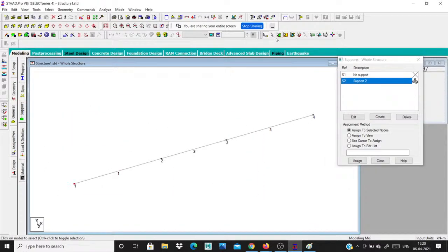First of all, this is a beam cursor, and this is the node cursor. You are working on the node points, but you selected the beam cursor. The beam cursor only selects beams. The node cursor only selects node points, right?